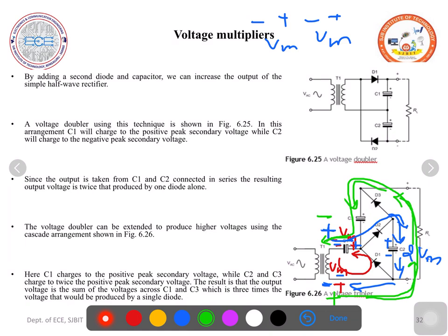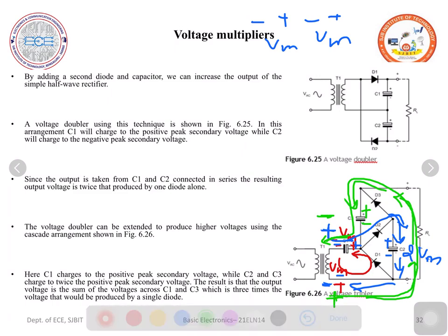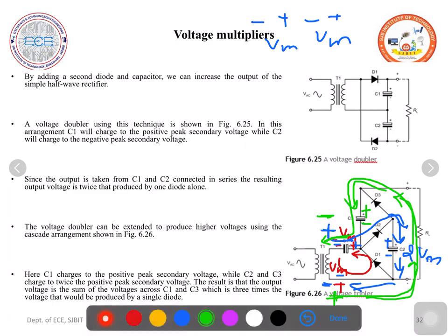It reaches the upper plate of C3 first, so it becomes positive, this becomes negative. What is the maximum voltage to which this capacitor C3 will get charged? Now this is the half cycle, green, here minus, plus, here it is minus, plus, so 2 Vm plus Vm, 3 Vm, but I go through along this.